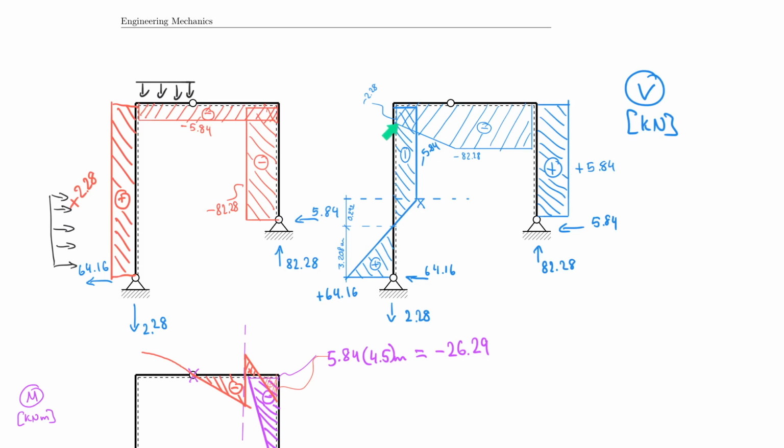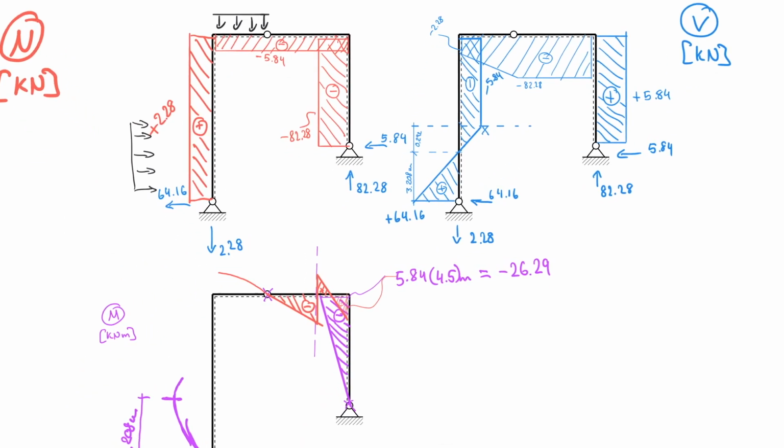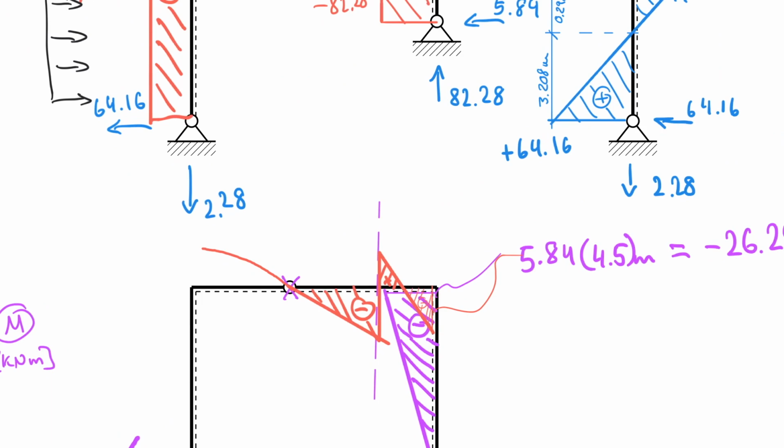So your shear force diagram does not go through 0 here. That means that I cannot reach a maximum here. Well, I mean, there will be a maximum relative to this, but there will be no change in slope, right? So I will have the maximum value right at the corner. So let's draw that. So it will look like this, and it will close here, and this is positive.